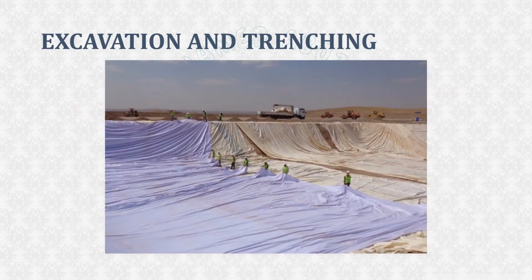All the pits used on the drilling location should be covered with a thick plastic sheet to prevent the contamination of soil with oil and contaminated water. A simple rule of thumb is to design mud pit volume with 3 to 4 times well volume.